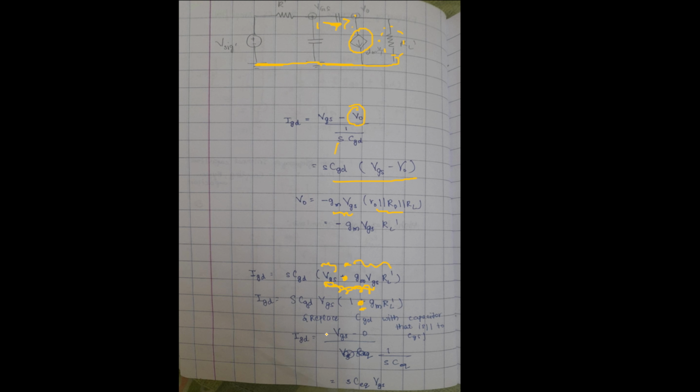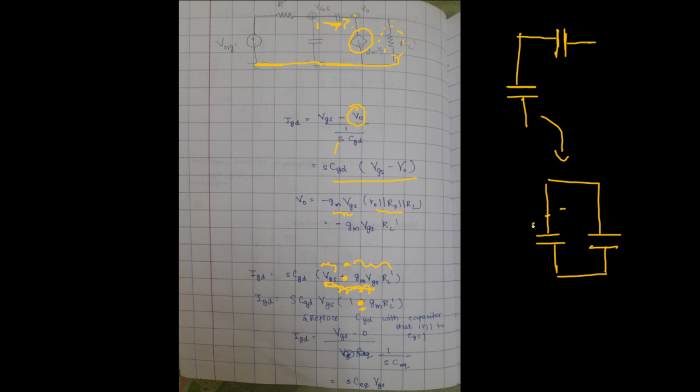Divided by the impedance. So, after doing this, we do the same thing that we did in a BJT when we had a capacitor like this and another capacitor like this. We reduced the circuit to an equivalent where we had two capacitors in parallel and then found the overall equivalent capacitance by just adding up these two. So for that, again, we need to find the equivalent circuit by equating the current with this voltage and taking an equivalent capacitance.